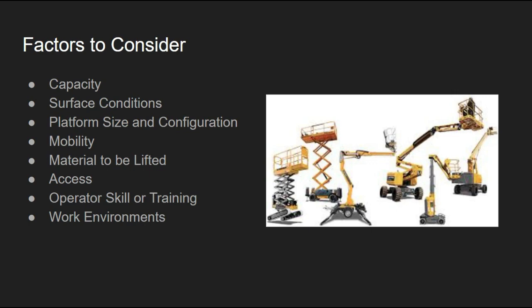Some factors to consider when selecting a machine are the capacity, the surface condition, platform size and configuration, mobility, material to be lifted, access, operator skill or training, and work environment. And remember, if your supervisor tells you to go over there and grab a lift, make sure that you choose the right one if there is more than one option. And don't ever be scared to ask, on your first time using this equipment, which the right one may be.